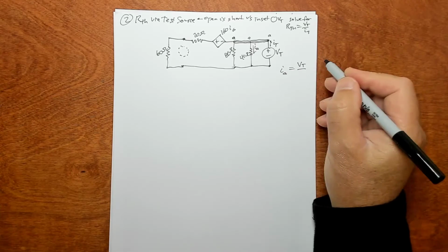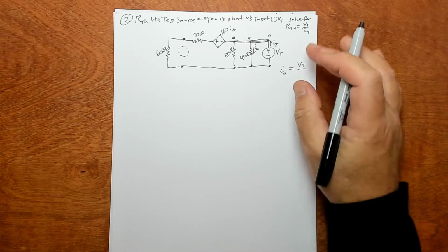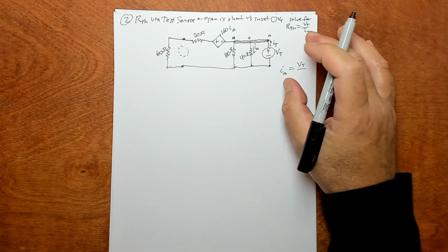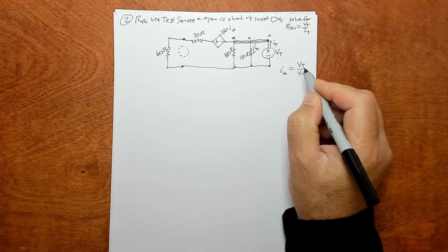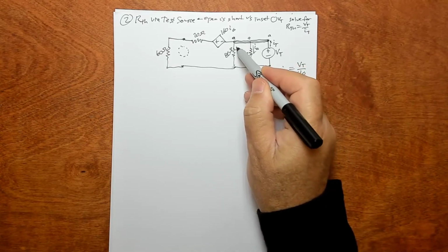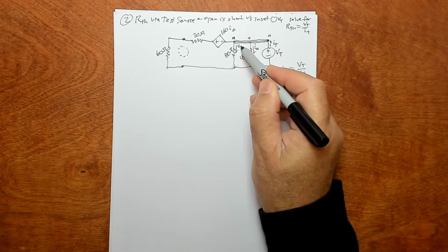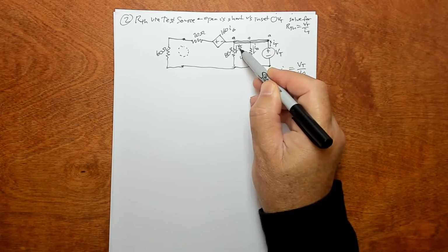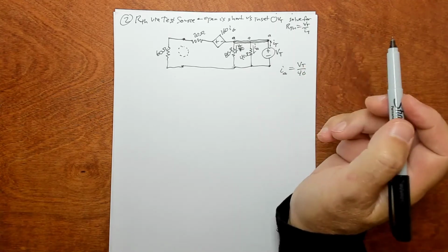It's not Thevenin any for this part of it. We're just trying to find R Thevenin here. It's a different problem. So now we're going to use VT over 40 for I delta. And this guy right here is going to be VT over 80. I'm going to squeeze it in here, just right there. VT over 80 is the current right there. And let's see.